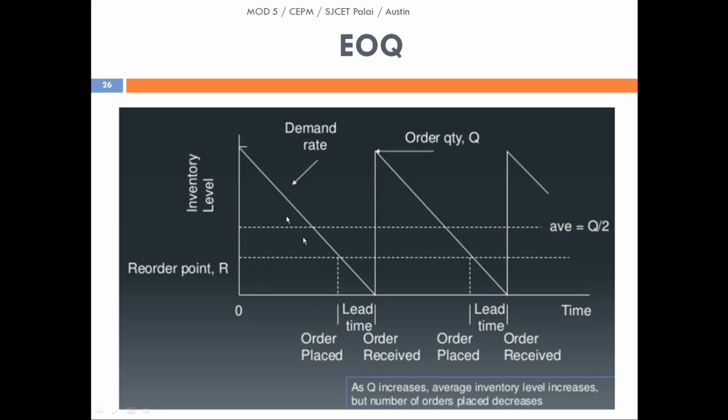As the time increases, the material gets used up for the process, and as a result, our stock or inventory reduces. The inventory goes on reducing, and at this point, this is half of the total quantity of inventory we had at the initial phase. So we have reached the half space, and then we could see that at a particular point known as the reorder point, when the inventory keeps on decreasing from the initial large point towards 0, we will place the next order, which is also known as the reorder point or the order point.